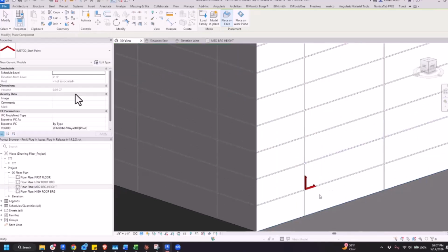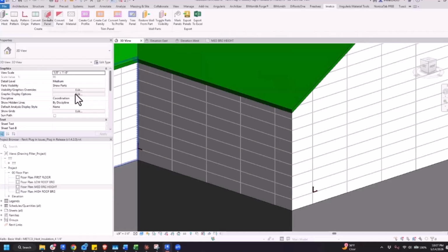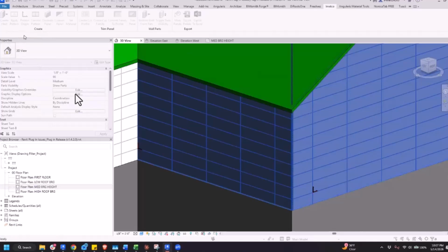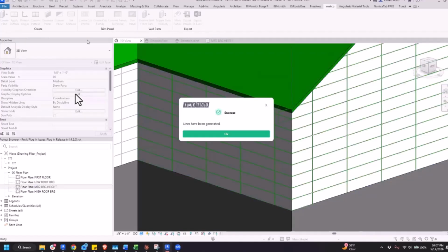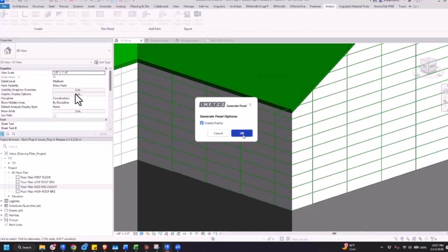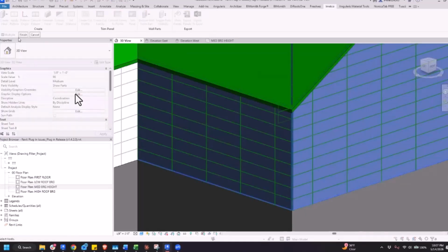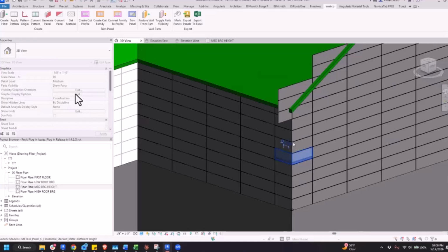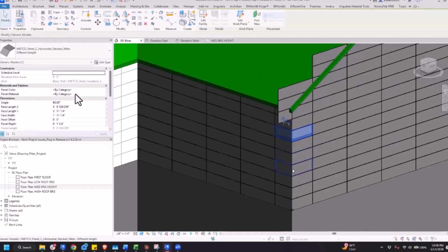So what we did to troubleshoot it, as Jonathan is doing, we added the origin point, and we went through the process. I need to convert the pattern. That's what you did. We just followed the same process that you guys normally do. We did not do anything different. All we did is add an additional origin point on the right wall, and when you created the panels, it did create the miter corner. So now that I create the panels, it should make mitered corners here. Now you'll see that these are actually mitered pieces.